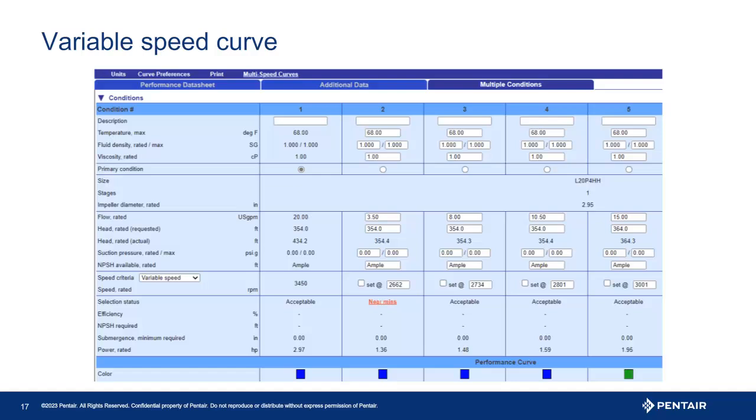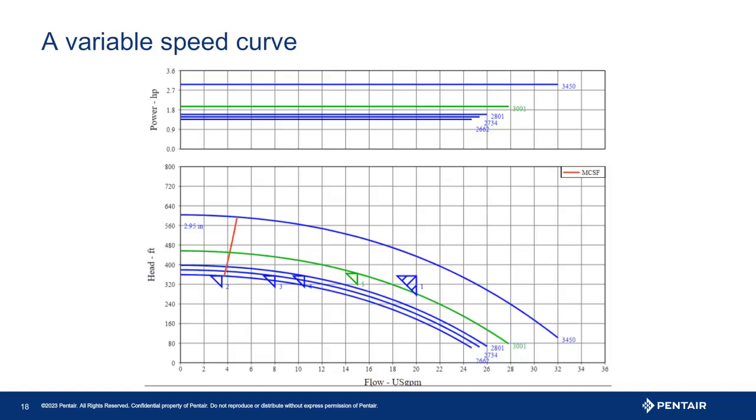Why is this? Here is the curve the data produced. And now we see the single shower is below the minimal constant sustainable flow. Now is this a concern? Yes, with a small tank it very well could be. This is why tank sizing is critical. But also, note how the horsepower consumption varies depending on the gallons per minute. How do you show the impact of a variable speed drive? You must understand total dynamic head.